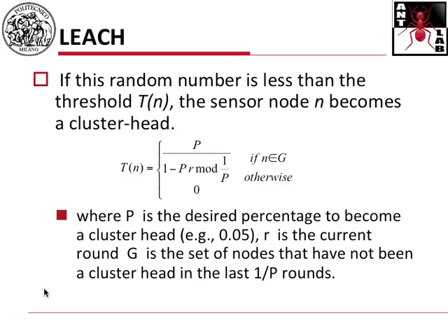If the network is not homogeneous from the battery point of view, meaning some nodes have more power than others, then this is not the policy which for sure prolongs network lifetime. So you should include somehow, in the cluster head selection process, the concept of remaining energy.